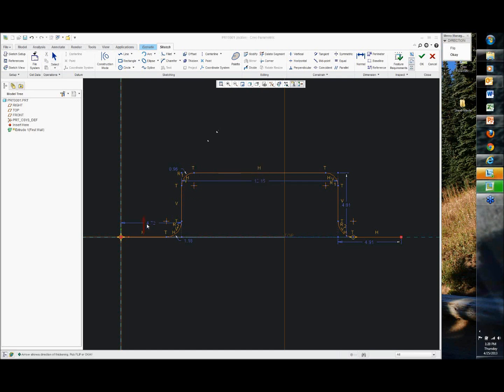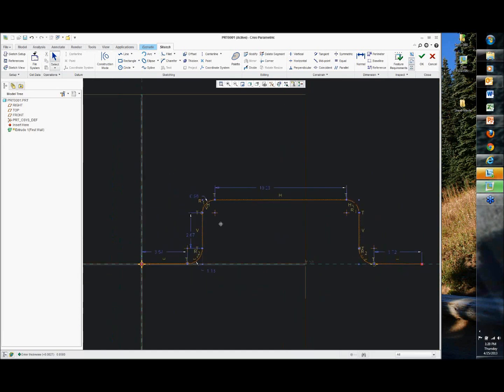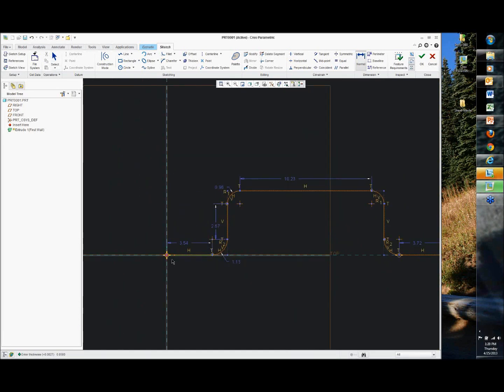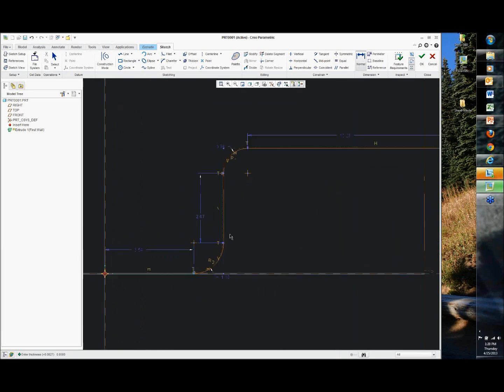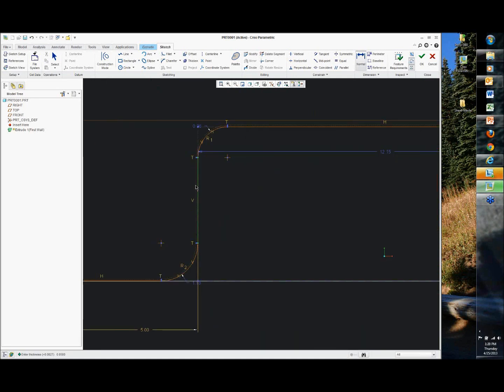I can thicken, right? So I get a choice of which direction. I can give it a thickness, and then I have the outside orange dotted line representing my outside material here. And the reason why I would do this is, again, I purely want to control the dimensions that make sense. I might want outside dimensions to everything. By having this extra thickened wall here, it allows me to go outside here.